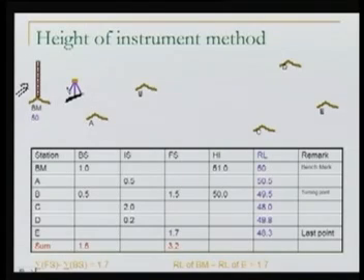Once the line of sight is horizontal, we will take a backsight. So what I'm writing here, this 50 indicates the RL of the point BM, 50 meter. The BS stands for the backsight, which is being taken by the level here, and this 1.0 indicates what we are reading here on this staff. So this is the observation which we take.